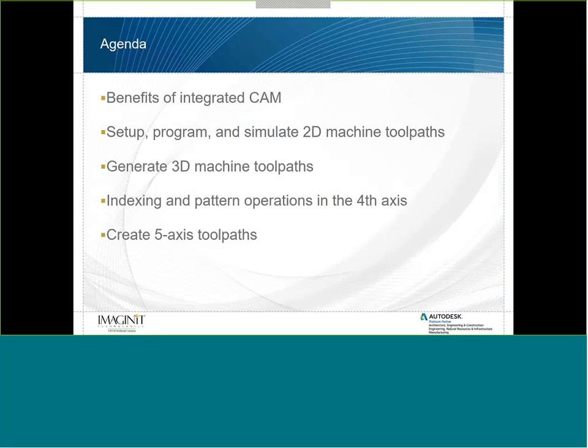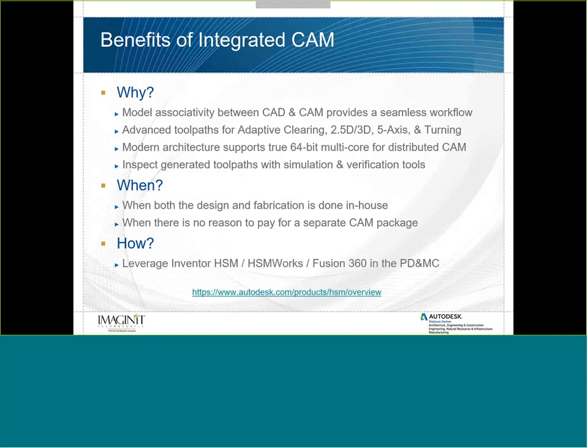So, without any further ado, let's talk about the benefits of integrated CAM. So the why around integrated CAM comes around having model associativity between the CAD and the CAM, providing a seamless workflow, especially when changes are made to the CAD model. Of course, taking advantage of advanced toolpaths, in particular adaptive clearing, to very quickly remove material in roughing operations.